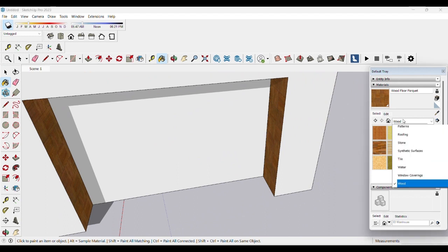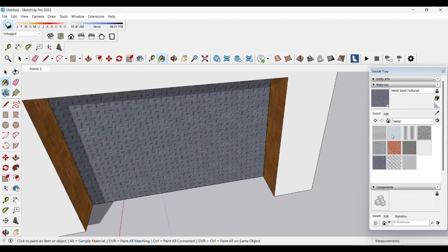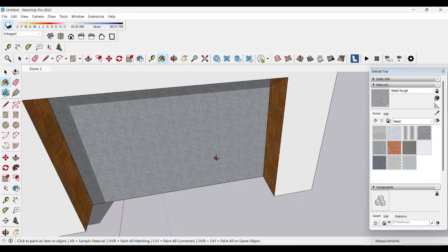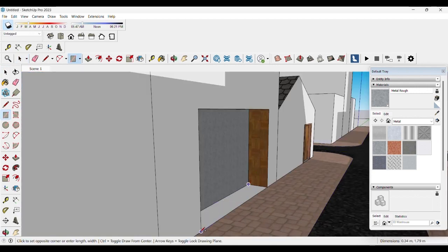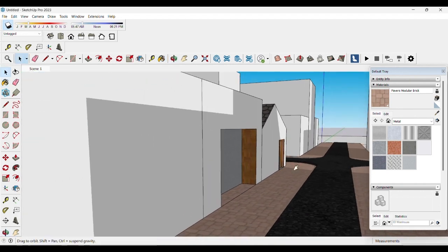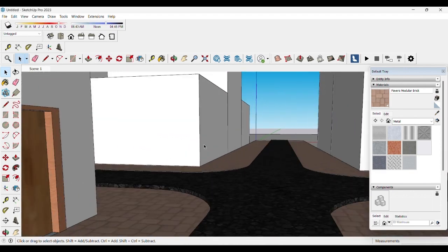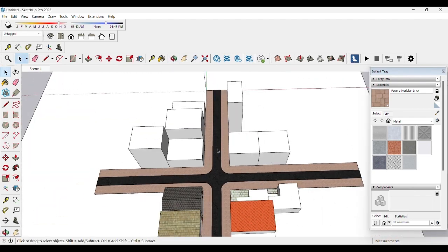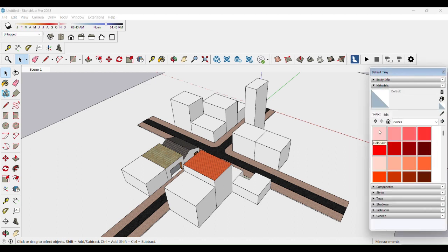Now let's create a garage. So a metal surface maybe. Let's keep it light and subtle. So we'll extend the pathway, create a rectangle, make that a group, use the dropper, select to match the material and give it a color. So now you get a sense of the magnitude of the area that we're doing because of the sloping roof and the door opening.